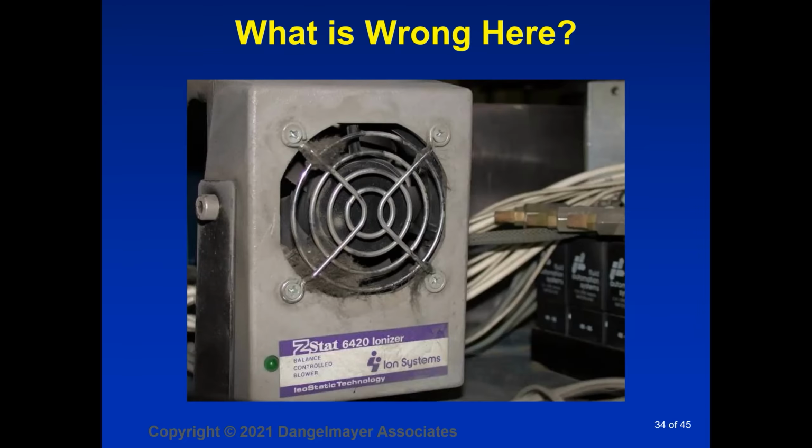Maintenance program is easy. Install the ionizer, check it after a month. If it's in balance and working, do nothing, go away. Come back in another month, check it again. Working, in balance, okay. Come back in the third month, slightly out of balance. Clean the emitter points, retest it. If it's now working, you know that your maintenance interval is 2 months.